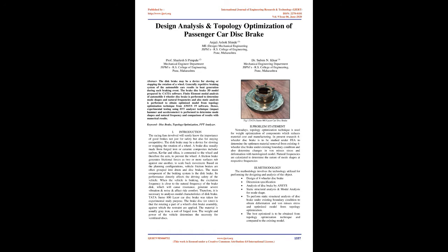The main component of the braking system is the disc brake. Its performance directly affects the driving safety of the vehicle. When the vehicle is braking, if the excitation frequency is close to the natural frequency of the brake disc, it will cause resonance, generate severe vibration and noise, and affect ride comfort. Therefore, it is necessary to analyze the modal characteristics of the disc brake.